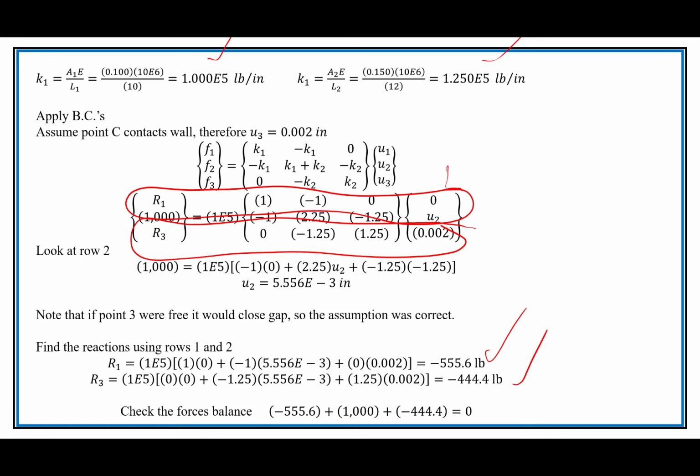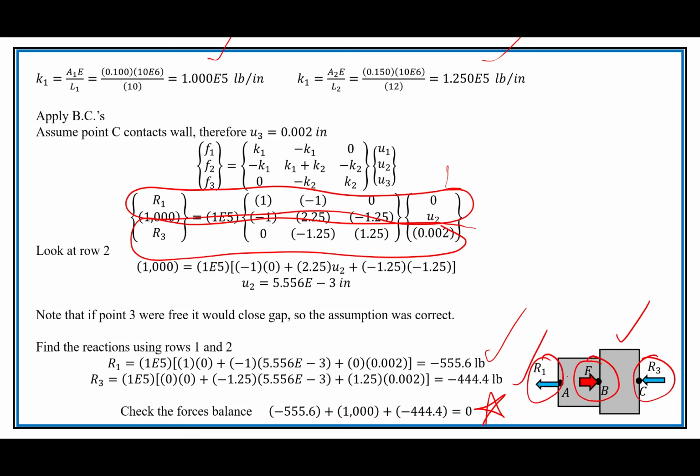And that's actually a really good thing to do when doing FEA on something, is to make sure that the force is balanced, because it is a numerical problem. So maybe it wouldn't. But you could see right here how the forces have to balance, right? You've got the applied force, and here are your reactions happening both at the wall on the left and the wall on the right. They better sum to 0. And they do.